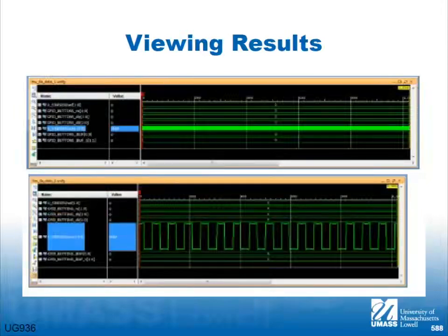Also, in these tools, they have simulators, or you can open third-party simulators from them. So what you can do, this is the point of the whole lecture right here. What you can do is compare what's going on in your chip to your simulation, or you can use this as a simulation accelerator. And that's where the connection between FPGAs and ASICs come in.